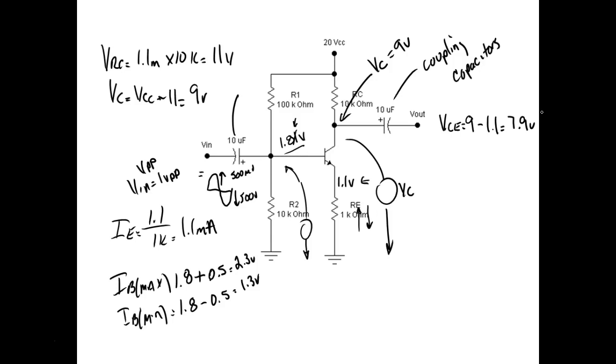And why is that important to know? Because that'll show us which side clips first. So what we would like is for this voltage right here to be 10. Now why can't we get it at 10? Because we're stuck with standard resistors, right?